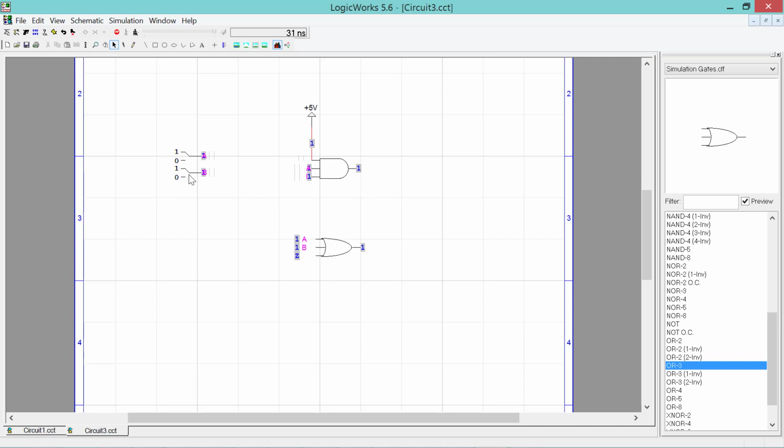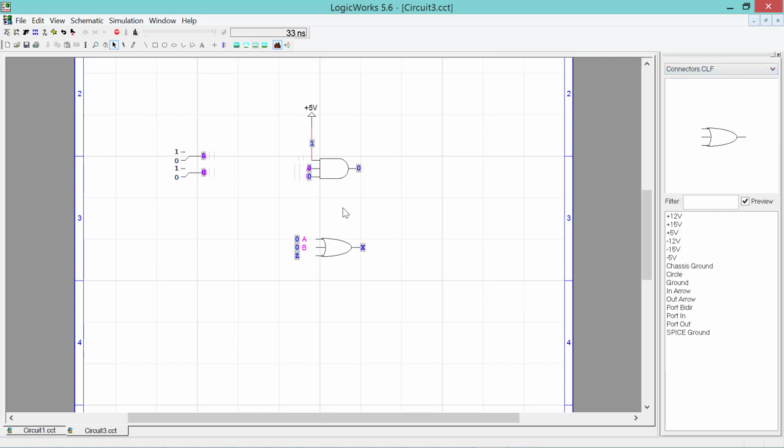However, if we have both 0 for A and 0 for B, then we have 0 ORed with 0 equal to 0. We would expect a 0, but because we have an unconnected input here, we will receive an X at the output here. So, going to connectors again, we can tie a logic 0 to this input by using a ground symbol here. Let's connect it. And we see 0 or 0 or 0 is equal to 0.